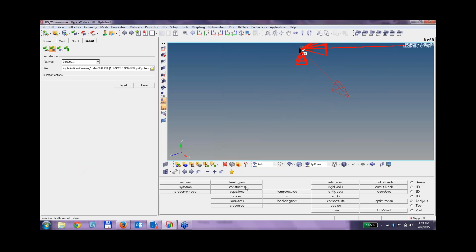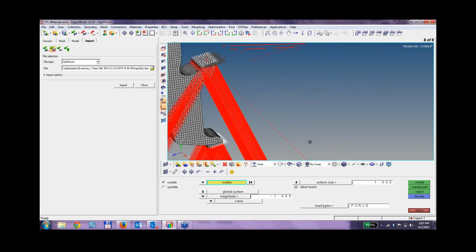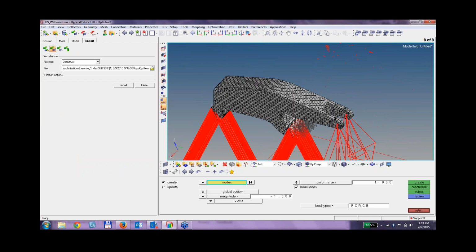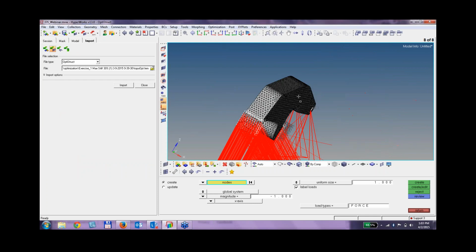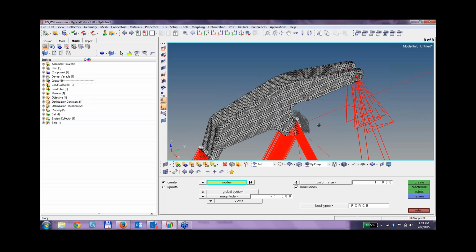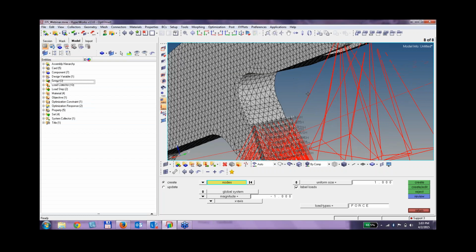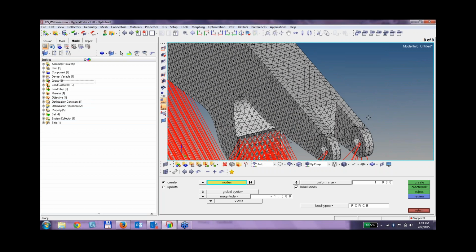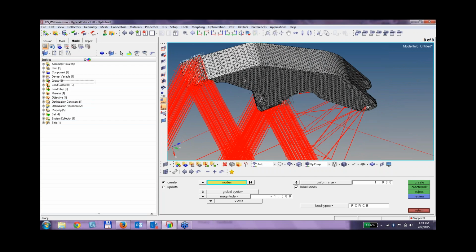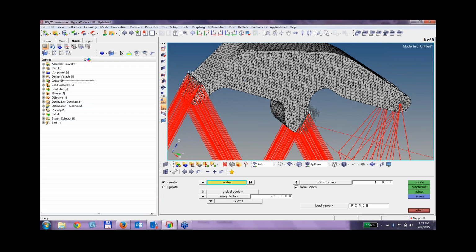And then we'll just come to my forces here, uniform size 1. That's better. Now you'll see this part was actually set up in Inspire, but I can read it into HyperMesh, and it's a great learning tool. You can set it up easily in Inspire and then see what it did to create the OptiStruct model, and you could take this OptiStruct model, make some changes in HyperMesh, and rerun it again. So there is a bit of interconnectivity between the two. You just have to know the secret hiding place as to where it's dumping the files.